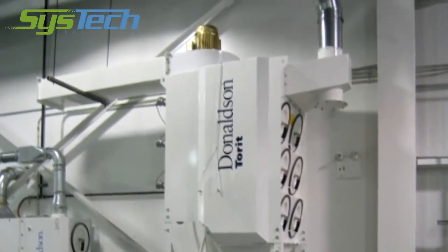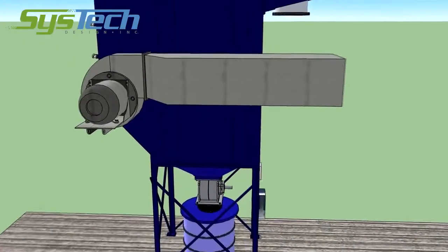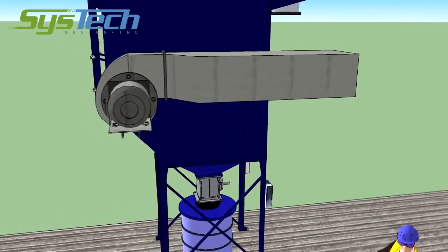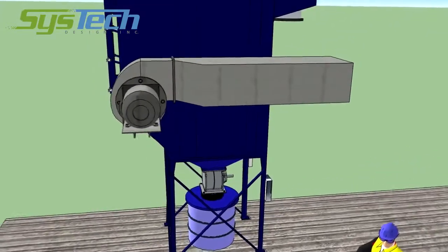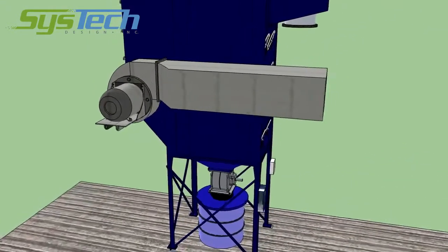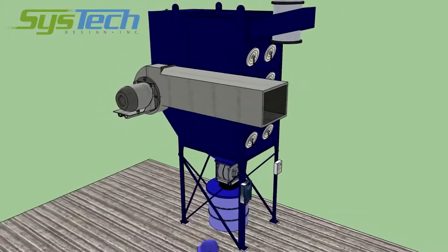If we couple fan selection with a variable frequency drive, we can expect significant energy savings, lower noise, and reduced capital cost. Direct-driven fans with a variable frequency drive are 30 to 40% less costly than a belt-driven fan with an outlet damper and motor starter.